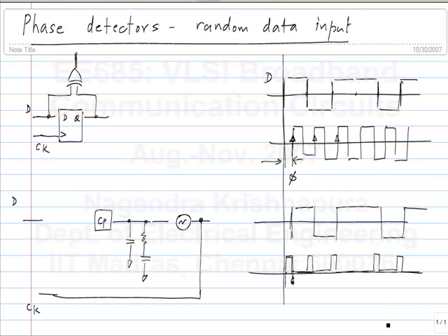So of course, the other thing you can assume, which is different from the case of a frequency synthesizer, is that you take the output of the VCO directly. So it is reasonably safe to assume that you have a 50% duty cycle here. Okay.